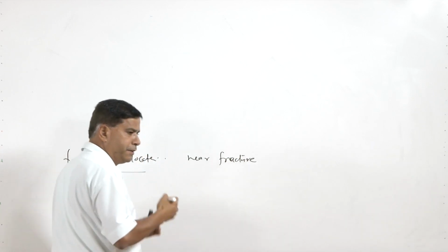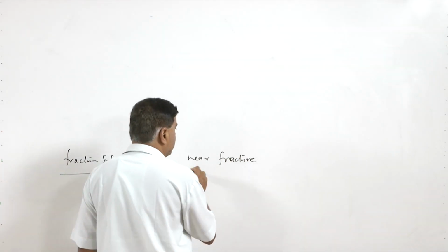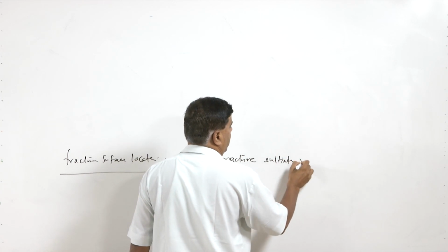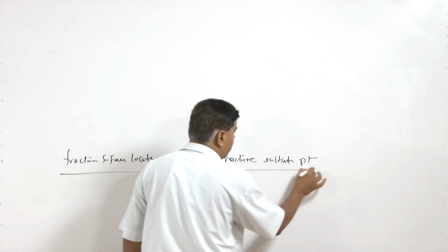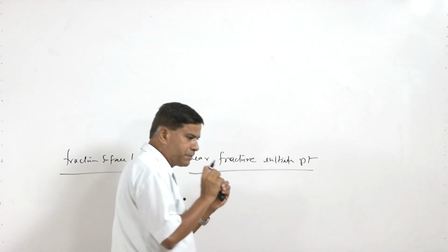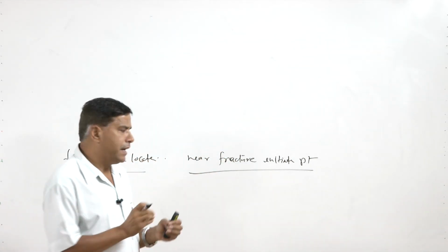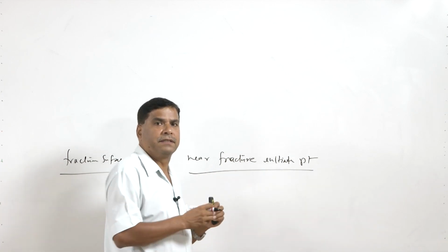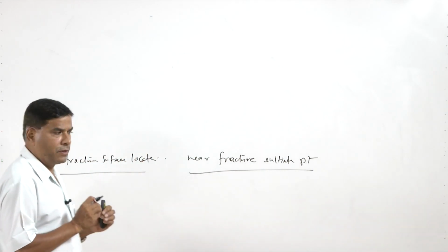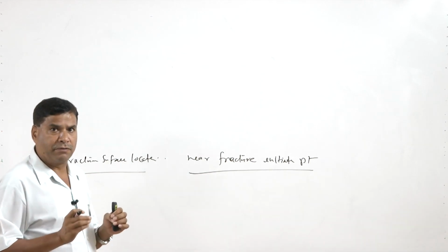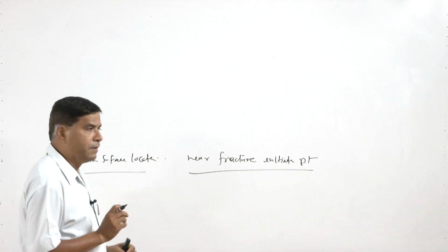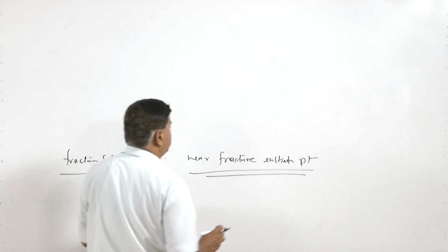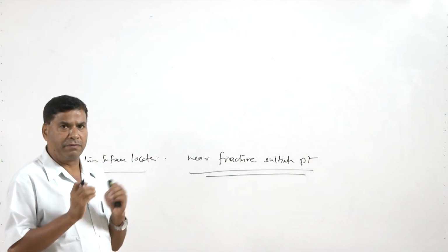If we are able to identify the fracture initiation point, then near the fracture initiation point the sample is collected normally from this location. This will help us to identify why the crack has nucleated, what kind of weakness in the component was present, because of which fracture has been triggered from that particular location. So, the sample is normally collected from the location where the fracture has initiated.